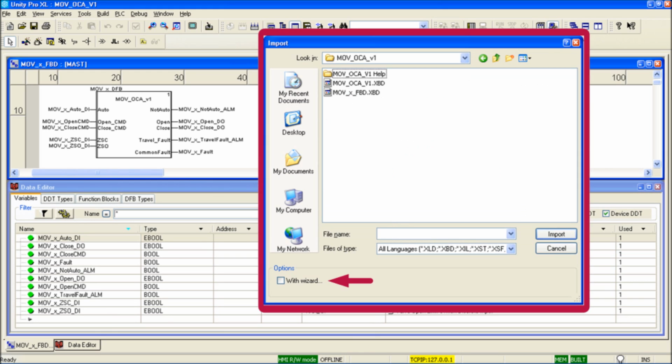You should know that Unity Pro also provides a means to accomplish a find and replace when importing a section. This is done by checking the box Use Wizard during the import process. The difference is that the DFB manager can and does go much deeper into the replacements made. This includes assigning values to the DFB public variables and modifying section variables' custom field content. All of this is done to optimize the DFB for ease of use by minimizing keyboard usage.